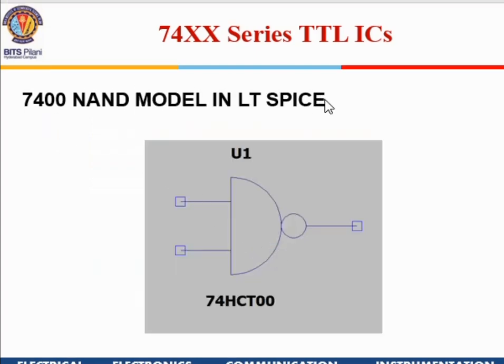But in the LTSpice model, we will pick up components like 7400. If you pick up a NAND gate, it will have input and output. We don't have to bother about the VCC and ground. Once we pick up this model, the software will automatically give the required power supply to that IC, so we don't have to make a connection of VCC and ground. But after 6 months, when you are so used to LTSpice, don't think that you don't require VCC and ground. When you are actually doing something practically on a circuit, remember that you will require VCC and ground.